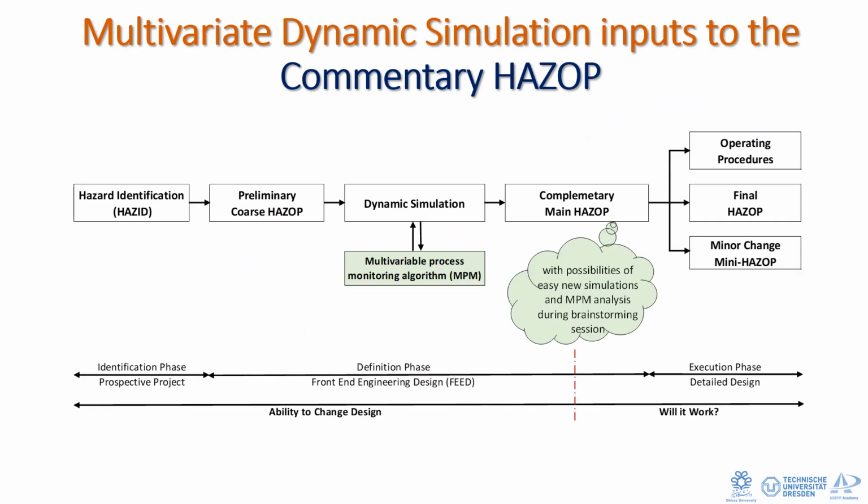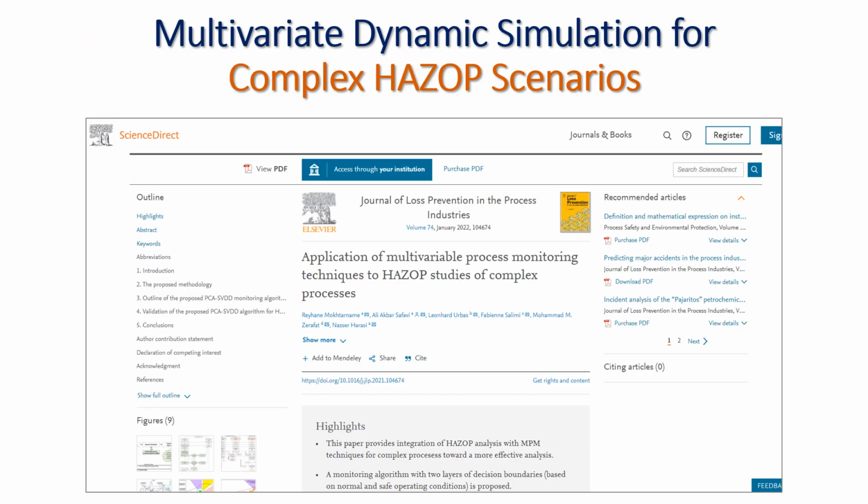The dynamic simulation results could be discussed in a complementary HAZOP brainstorming session, as well as in further studies such as alarm and seal assessment. During the operating phase, this digital twin, which encompasses all the EPC rationale, can be used for troubleshooting and operator training.